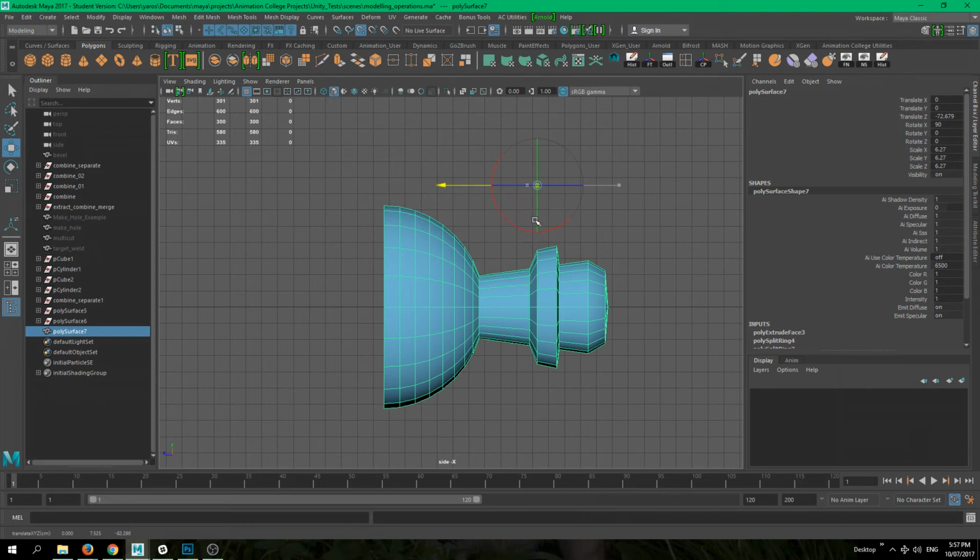So it's snapping to the vertices. And all we need to do is snap it to those verts on the left. And it doesn't let me go any further because there are no more vertices anywhere. So I've snapped it here. And I could also snap it to this point as well. So to snap it here, I could either use my X snap, because I could snap to the grid, or I can use V snap again. So now I need to reconfirm which axis I'm using by dragging this blue arrow around, to tell it, hey, I will be working with this one. Press V and hold, and then start doing this again. So now I can snap it to the middle point over here.